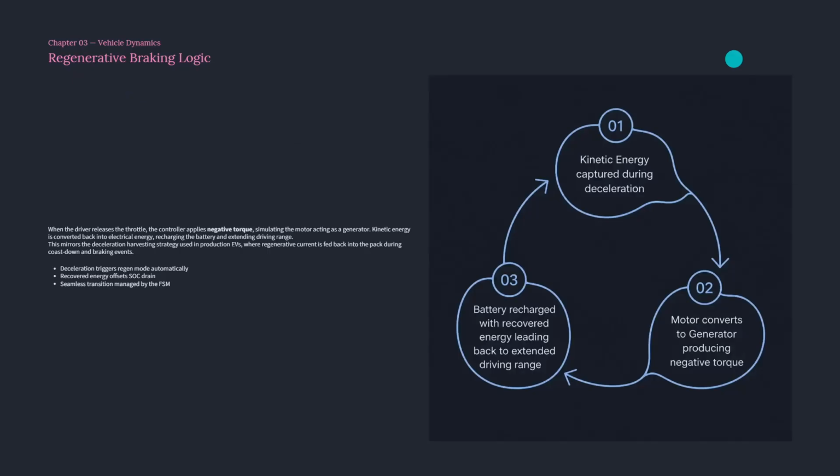Now we come to the regenerative braking logic. What happens here is that when brake input increases beyond a threshold, negative torque is applied. Higher brake, stronger deceleration. Moderate brake, smooth slowdown with partial energy recovery. Very low brake results in almost no regenerative effect and the vehicle coasts. Braking is not just stopping, it changes both speed and energy flow behavior.